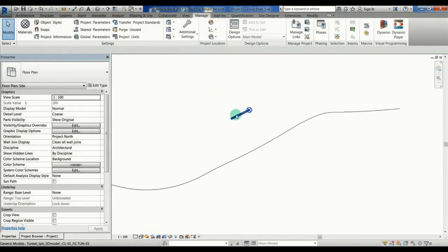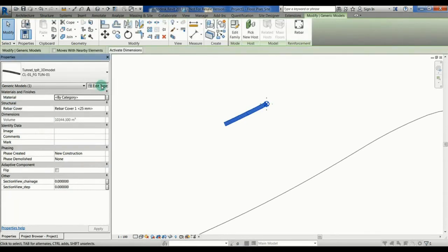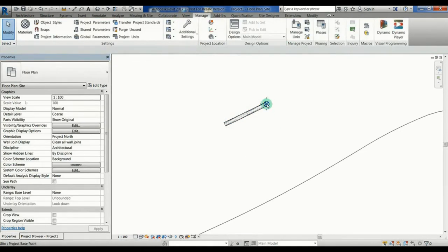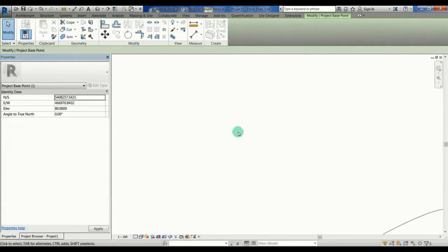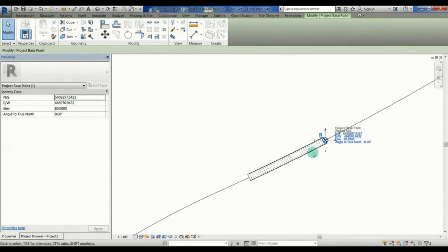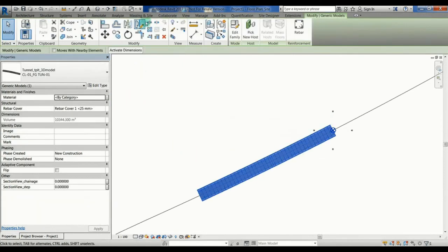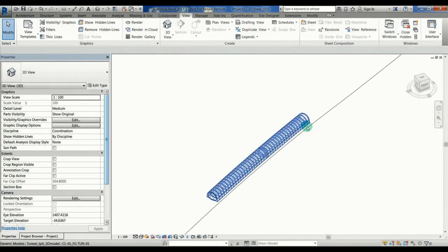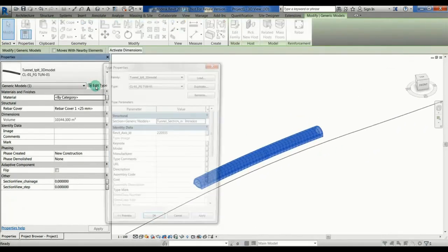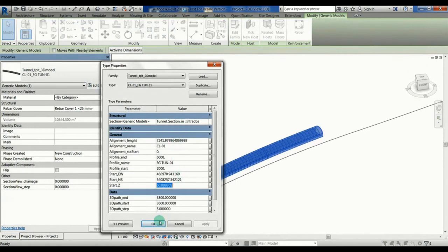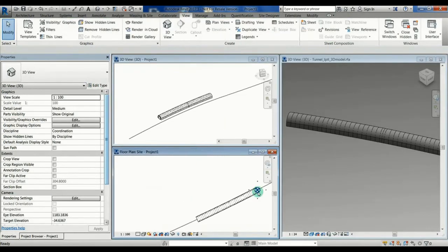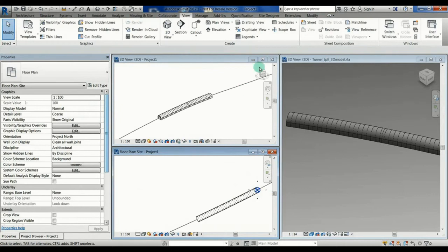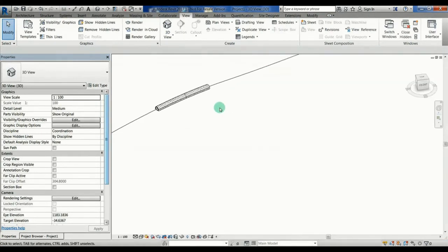It's possible as well. So I will just change the Northing now. So it's just copy and paste, okay? And you can see that when I change the Northing, the tunnel will fit exactly at the right place in the project according to the site file. So according to the main 3D axis. So now we just have to change the Z, so it's not the same. Okay, just change the coordinate here. Okay, and done. So you have your tunnel exactly at the right place in this project.